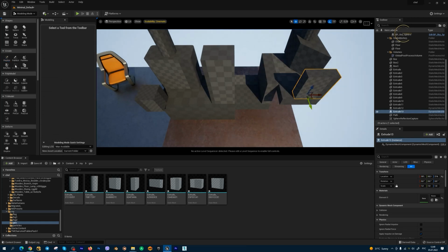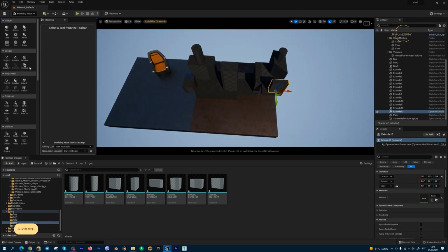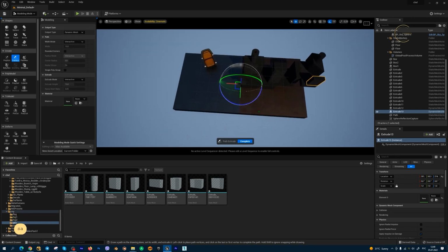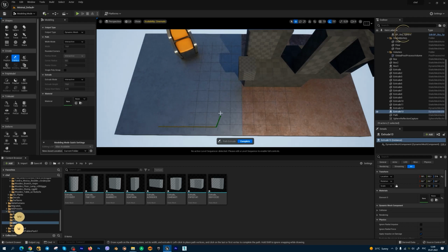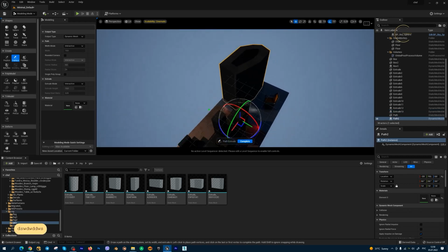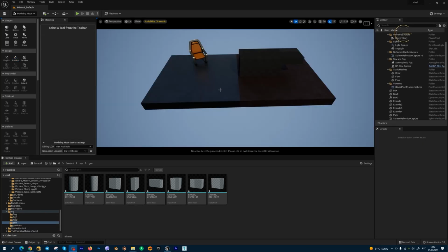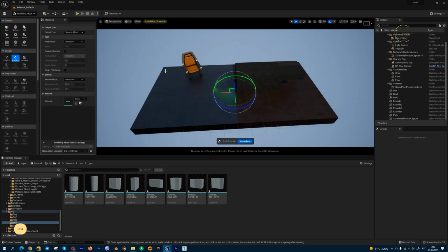The next powerful tool is path extrude. This is the same tool, but you can create different paths using it. Also, we can create a polygon to align to your surface, and we can create this type of path. This could be, for example, walls for an interior or a castle. We can create them using this method. Also, we can create opened walls, opened geometry using this path extrude tool. It's very powerful to create, for example, walls.